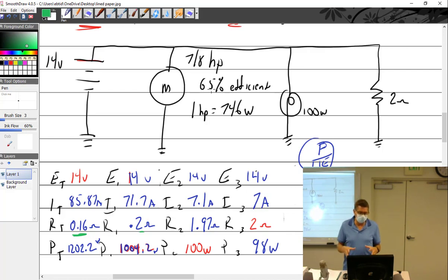Then you would evaluate the circuit and say, okay, I'm running 14 volts at 71.7 amps. Then you would take the run, how long it's going to go from your source, your battery, to the motor. Of course, I would have relays in there to operate this and all kinds of stuff. Based upon the load and how far the run is, you would figure out what size wire you had to use. Because you can't just pick a wire. It's not like, well, I like the blue wire, it sounds good. No, you got to pick the right size wire, or you're going to create smoke in the cockpit.